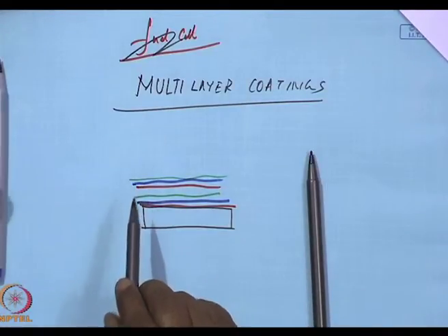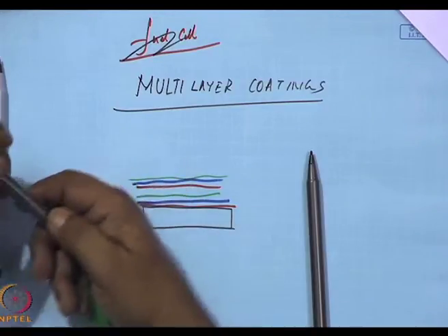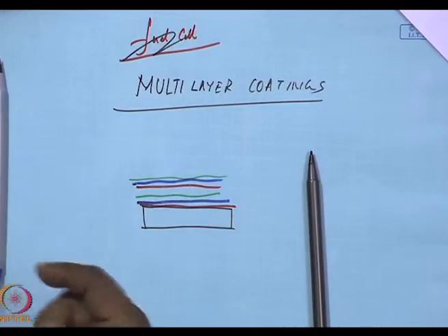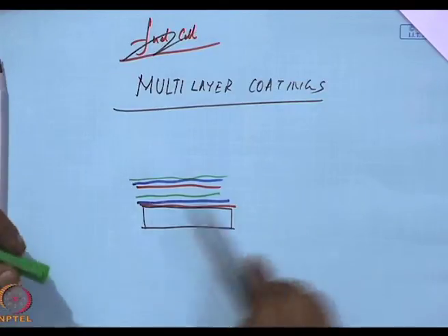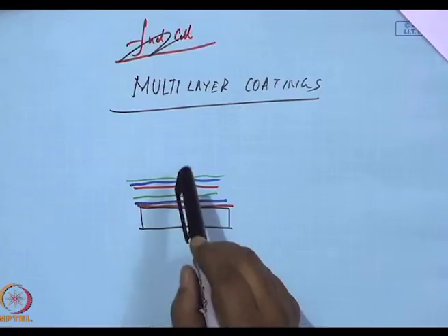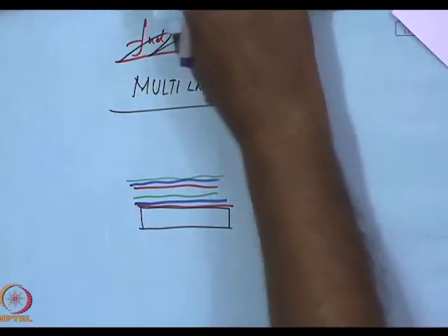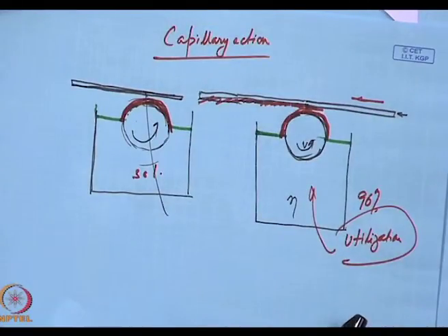this one. Now, these coatings are made by the physical vapor deposition process. But as I said, physical vapor deposition is turning out to be an expensive one. So now alkoxide based sol gel processing is being increasingly used to deposit such layers. And which is the best process to deposit this other than this capillary method?